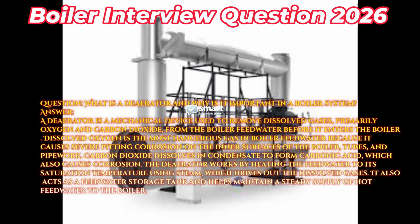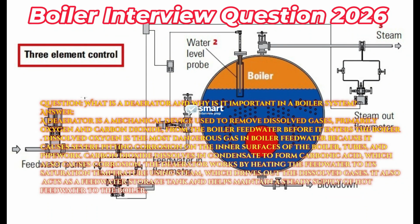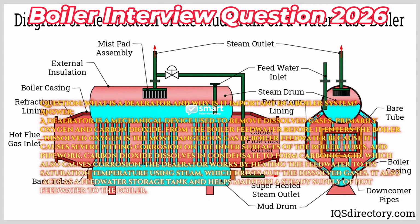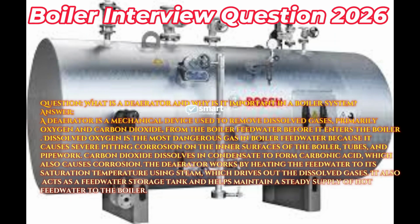A deaerator is a mechanical device used to remove dissolved gases, primarily oxygen and carbon dioxide, from the boiler feed water before it enters the boiler. Dissolved oxygen is the most dangerous gas in boiler feed water because it causes severe pitting corrosion on the inner surfaces of the boiler, tubes, and pipework. Carbon dioxide dissolves in condensate to form carbonic acid, which also causes corrosion.